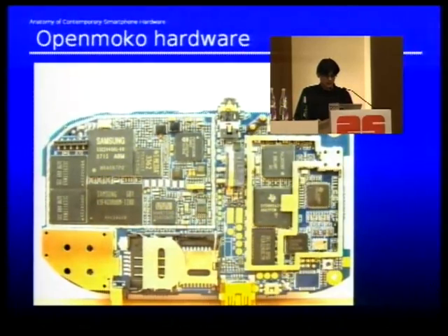And the section which has the frame for the shielding cover over here is the actual GSM modem side. This one is the baseband processor, then we have the DSP over here, some flash and RAM in one package down there, and this is RFPA, I think, over here, basically. And the section here, which is completely covered, is the GPS unit that is separately shielded because GPS has very sensitive signals. So this is basically how something like this looks.